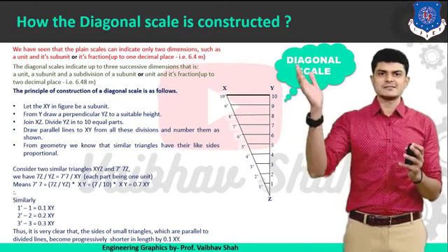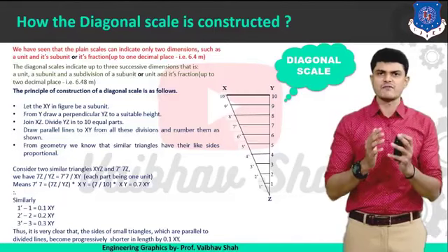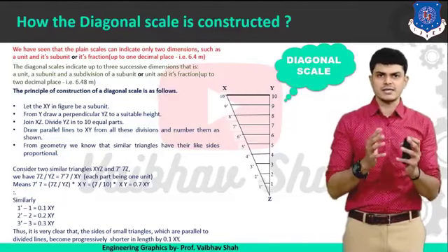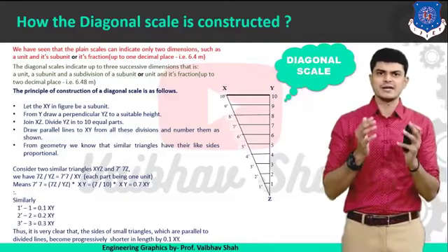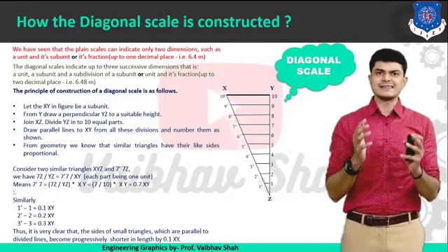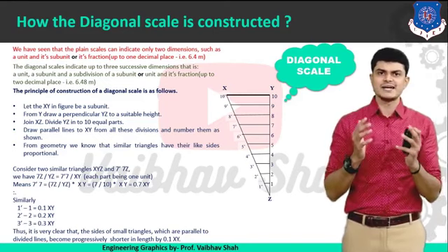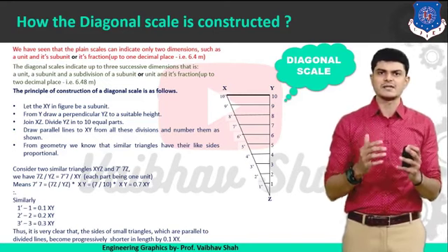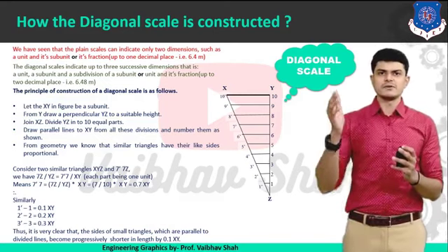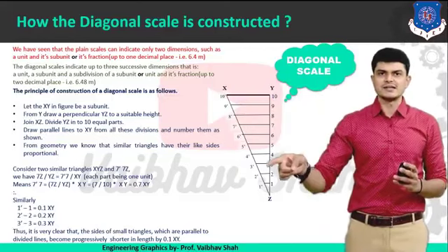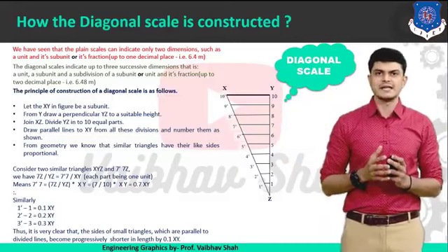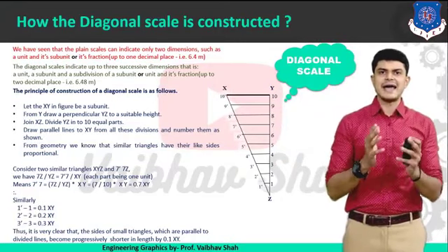have now divided this line xy into 10 equal parts. But in our case, we have not shown the 10 parts of this line itself. Instead, we have generated 10 lines in such a way that they are successively of a smaller length compared to the previous one as we go downwards. So this inclined line generated after the construction of the scale is nothing but a diagonal scale.